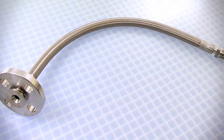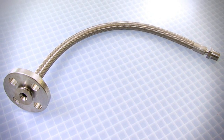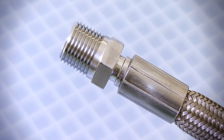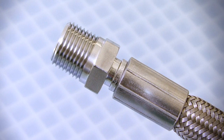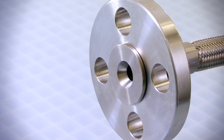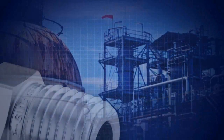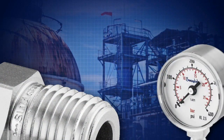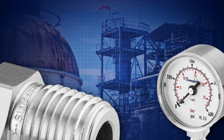After identifying the specific threaded end connection and flange type, it is determined that the appropriate end connections are a 1/2 inch stainless steel male ISO BSP tapered end connection on one end and a 1/2 inch stainless steel ANSI flange on the other end. Note that it is important to identify the thread type and pressure rating to ensure proper installation and system media containment.